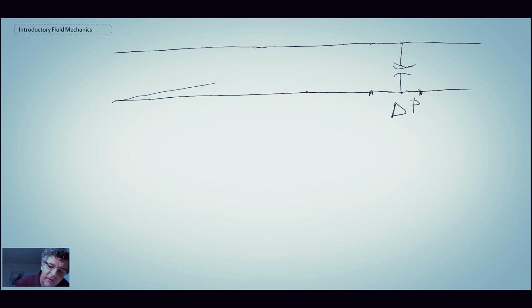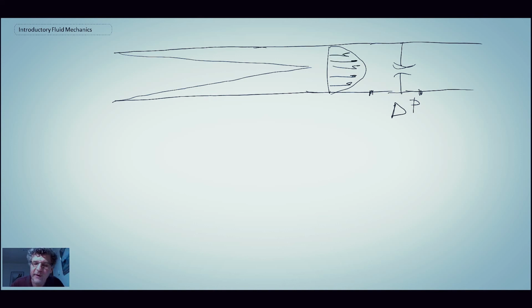That would be a case where you certainly want your potential core to close because you want to have uniform flow, and because that's how that flow meter has been calibrated, be it laminar or turbulent. It would have different conditions, but certainly when you're doing flow metering, you want uniform flow. You don't want to be sitting up in the potential core, whereas in the case of the wind tunnel, you would actually want to be in there because you'd have nice clean flow in that section. So just don't get confused with that, why we would be wanting to go in the potential core. Usually we don't. For engineering applications, just in this particular case we did. So anyways, that concludes entrance lengths and the example problem.